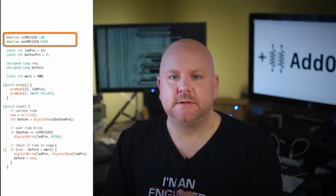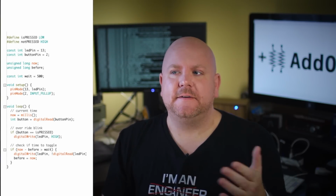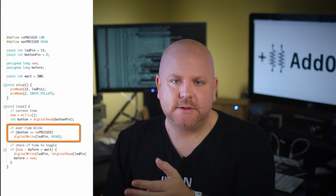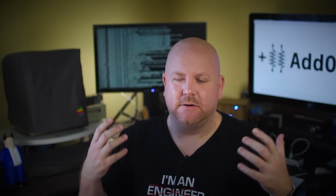And so what I actually do in my programs is I create define statements to define when the button is pressed and not pressed. And that way I can look at an if statement, and the if statement will be: if button equal pressed, then go do something. And I find that way easier to read and understand than if button equal low, because I don't really know what low means. And so that's just one tip, is maybe use define statements.